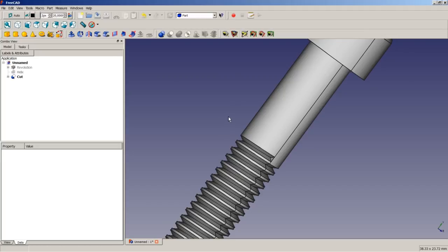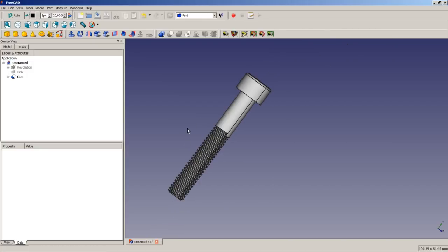That's why we will apply a little cheat there as well by changing the value to 2,386 millimeters, and then the Boolean operation will succeed.